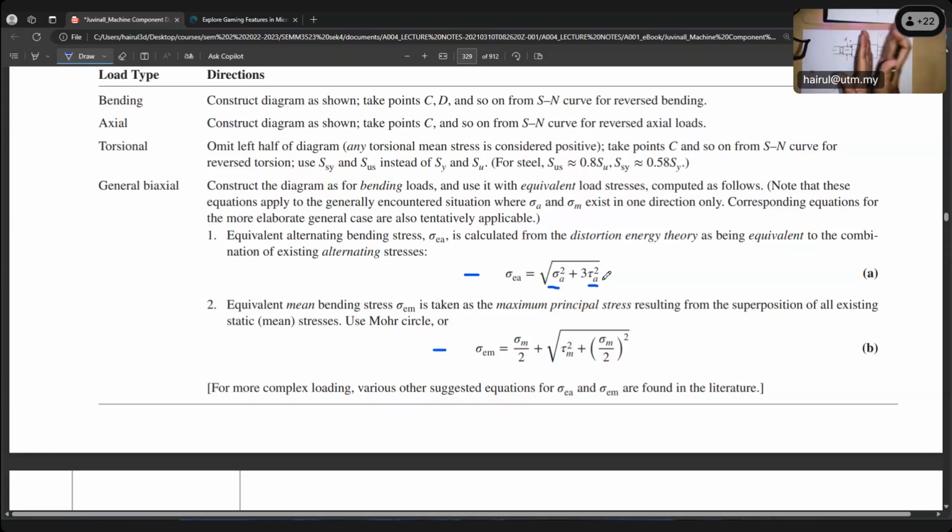Because the shoulder means the pulley cannot move to the left. It's blocked by the shoulder. Without it, if your shaft is just plain and you mount a pulley, sometimes it can slide, and nothing locks the pulley from shifting left and right. So the shoulder blocks the pulley from shifting to the left, and to block the pulley from shifting to the right, we have a notch and then we place a snap ring here.